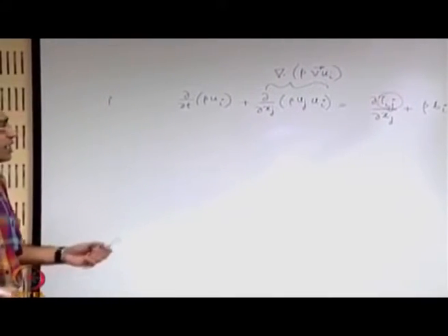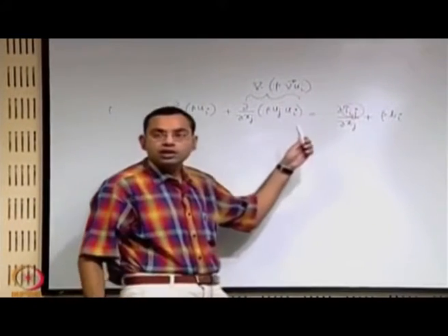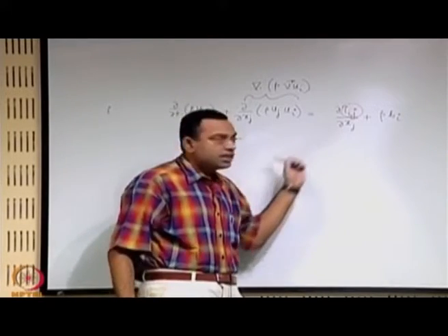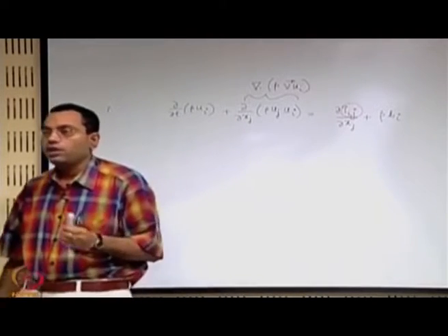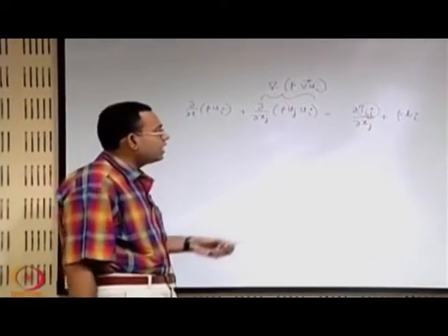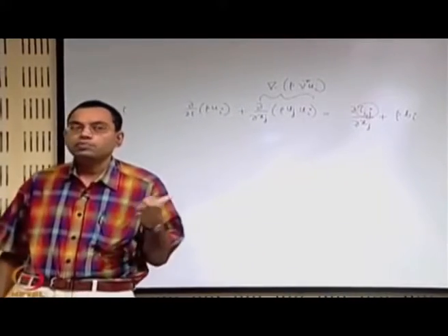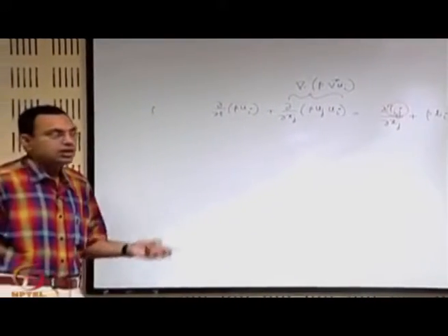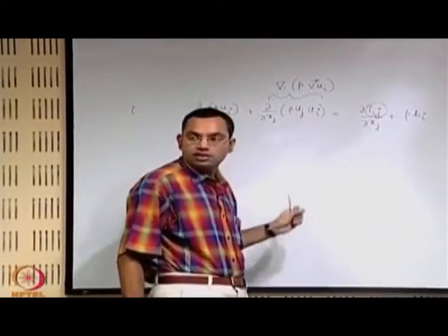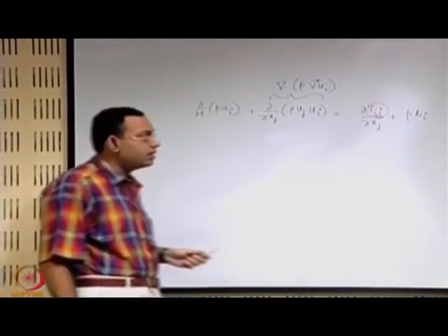We figured out that in the most general case you might require 81 independent constants to express the deviatory component of tau ij with the rate of deformation. But at the end we found that if you have a homogeneous and isotropic fluid, it boils down to two scalars, and we could identify the important scalars for expressing the deviatory component of tau ij.